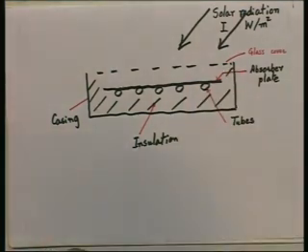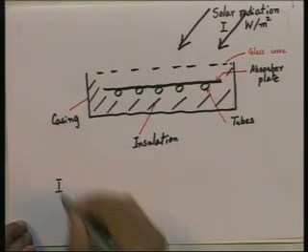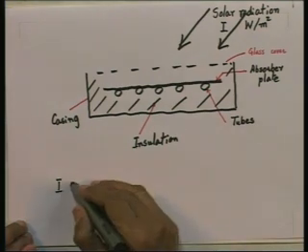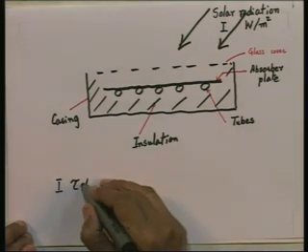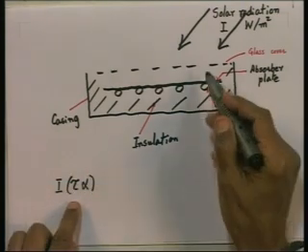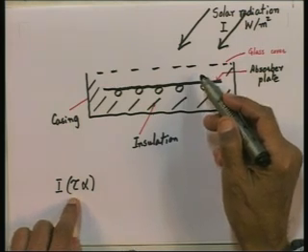So, if I were to write what is happening to this flux which is falling, I will say I is the radiative flux falling, and tau into alpha is the amount, where tau is the fraction transmitted through the glass cover, which is usually a number like 0.9, 0.95.